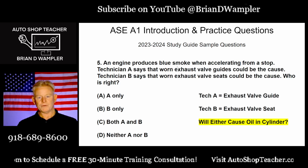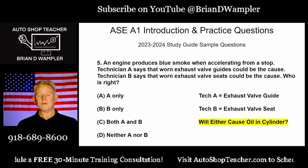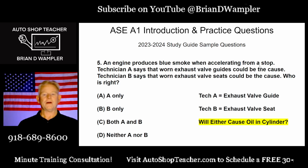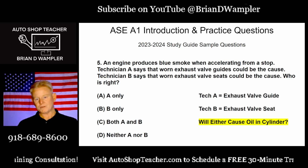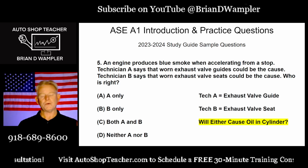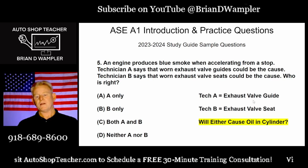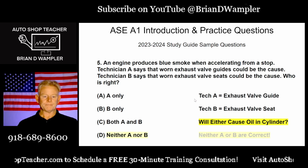We're talking about blue smoke, and when I say will either cause oil in a cylinder, I'm including the when accelerating from a stop. So we're not talking about sitting overnight. We're not talking about parked at the grocery store or grandma's house at Christmas, okay? We're talking about the engine's running, there's no blue smoke, you accelerate from a stop sign. Will an exhaust valve guide or exhaust valve seat suddenly allow oil to enter into the cylinder when you accelerate?